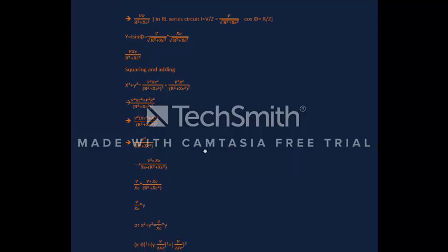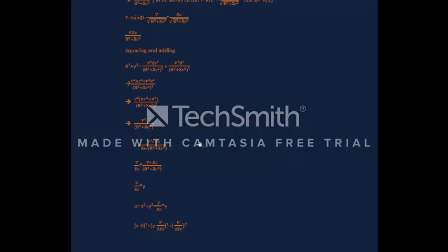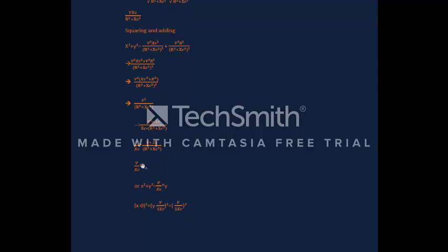Let's square these both equations and add them together. We get x square plus y square is equal to V square XC square upon R square plus XC square the whole square, plus V square R square upon R square plus XC square the whole square. This turns out to be V square upon R square plus XC square. So we get an equation saying x square plus y square is equal to V upon XC into y.